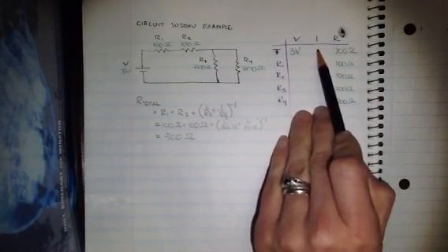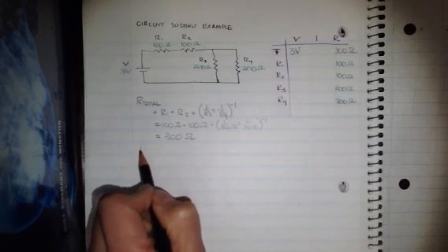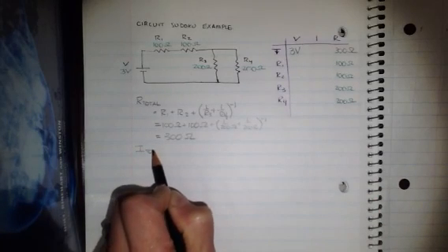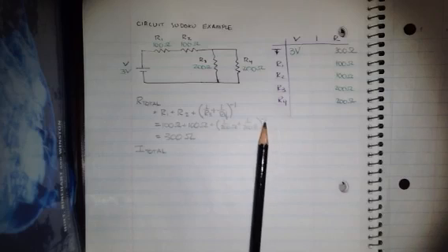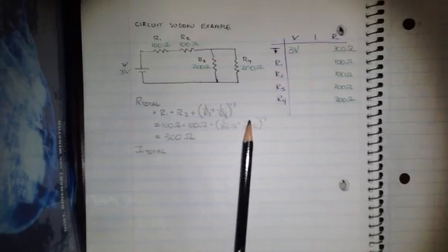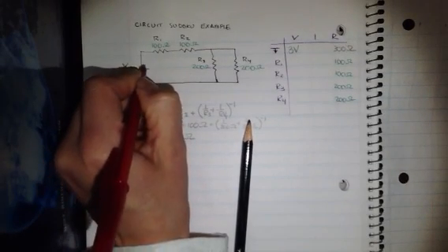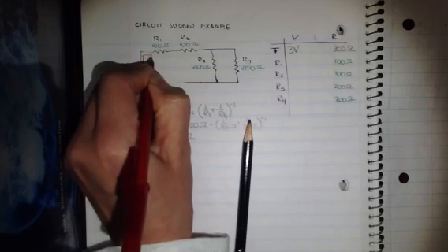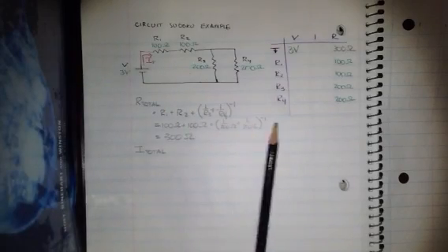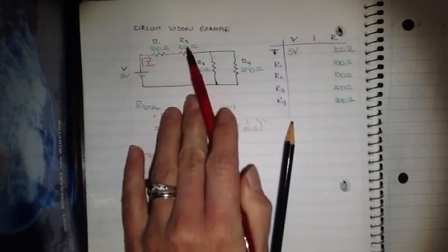So now my strategy is going to be to find the I total. Let's analyze the circuit, figure out what's going on with current. I total is the current that exits the battery, flows through resistor 1 and resistor 2, then branches here and here.